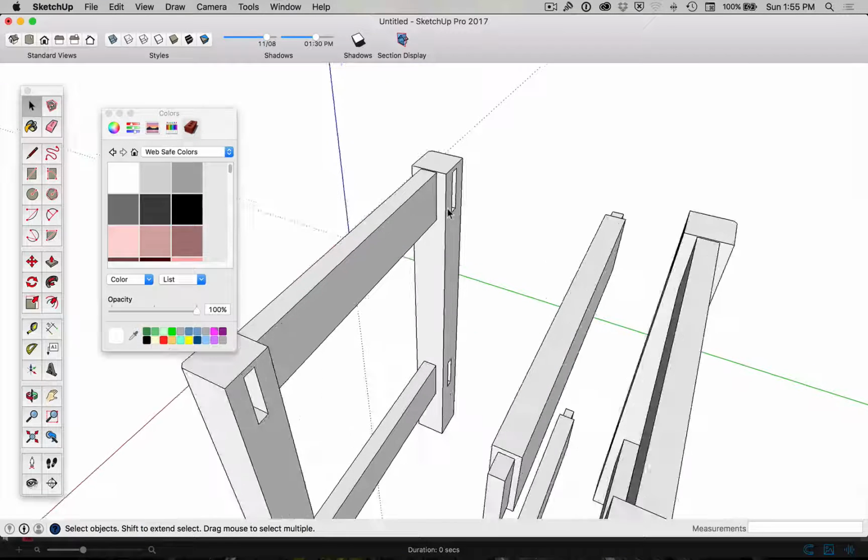I'm going to measure, just keep this little figure in your head, from here to here, because that is an equal distance as 310 between the outside edges, or the inside and the outside, so the overall distance of that mortise. What I'm going to do is rotate them, M. How can I rotate them? I haven't made them into a group. So if I made them into a group quickly, I could do exactly what I did before.